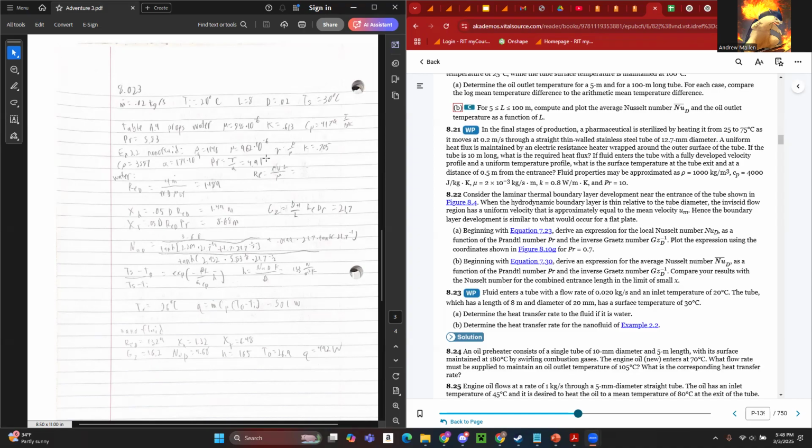So first thing we're going to have to do is find the Reynolds number. This is important for determining some thermal boundary conditions, such as the length of the thermal and hydrodynamic boundaries. So normally the Reynolds number is found by rho u L over the dynamic viscosity.